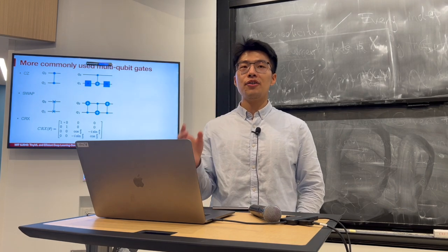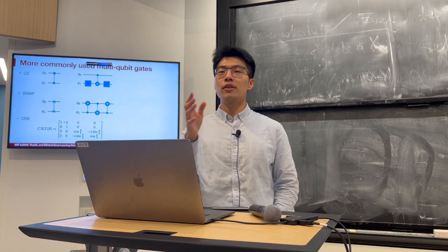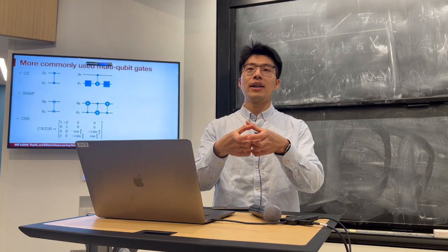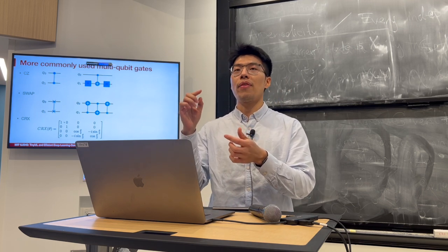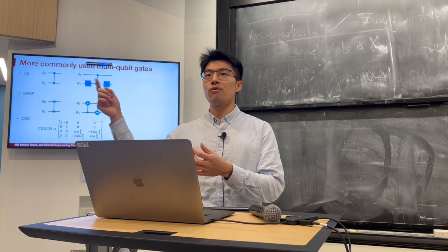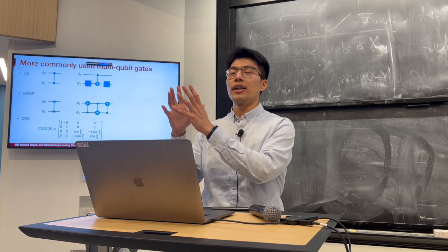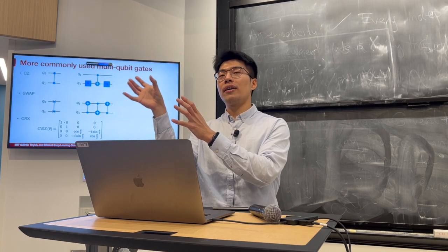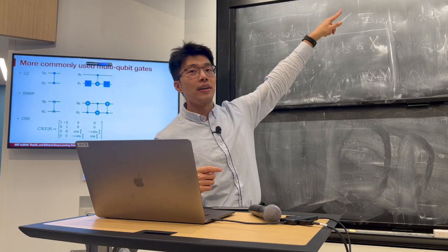The actual implementation differs for different technology roadmaps. On a superconducting chip, for example, we fabricate artificial qubits, and the gates are implemented with microwave pulses. We have a transmission line to the qubits, and we can compute the shape of the pulse. The area under the shape determines the rotation angle theta.